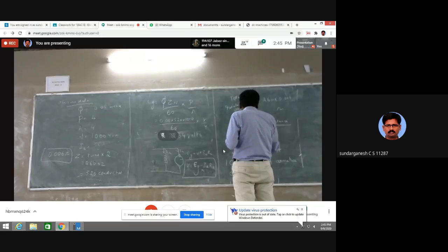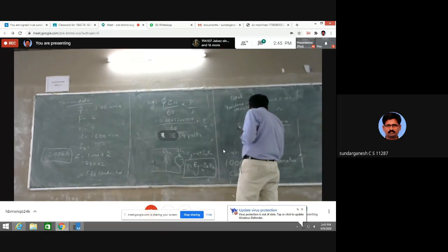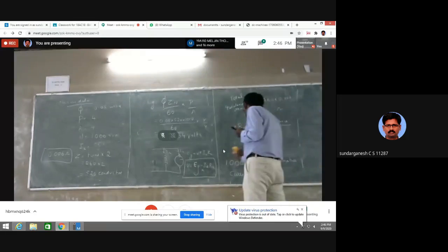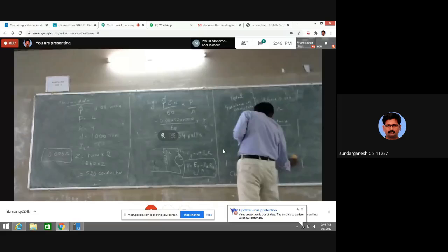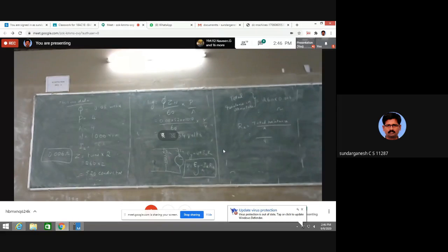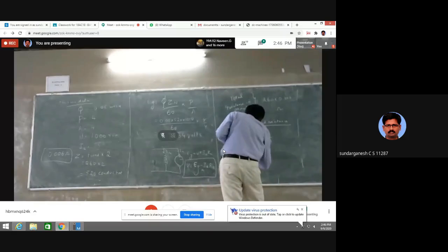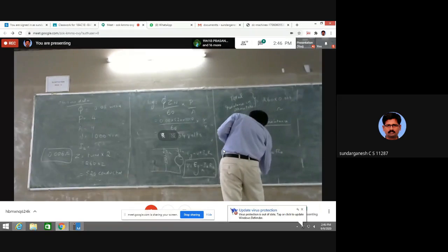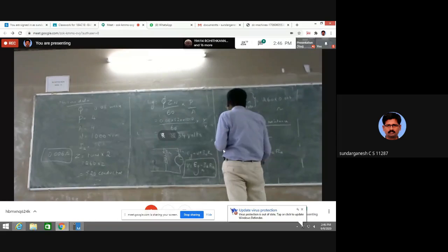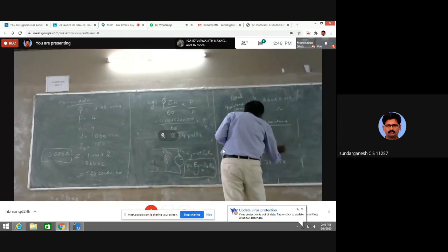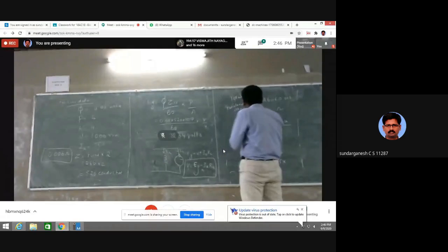So whatever value you get here, you divide by 4. Then you get RA. After finding RA, you can apply this formula: V equal to EG minus IARA. EG you know. EG is 693.34 minus 55 into that RA value, and you find the terminal voltage.